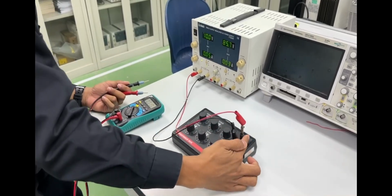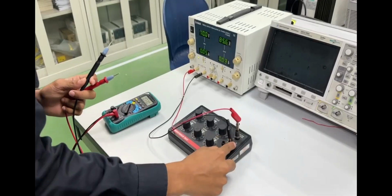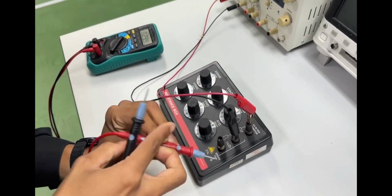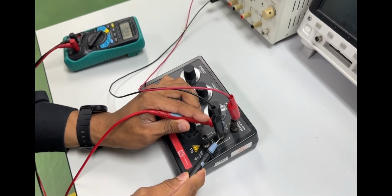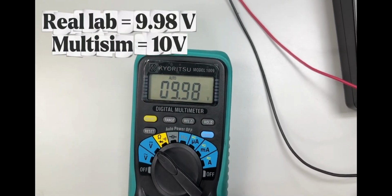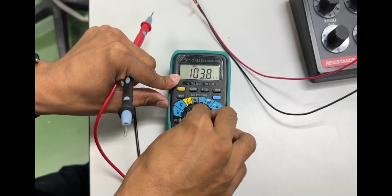For measure the voltage, we put from the DC supply, which is the positive probe, into the positive resistor. This one, and then for the negative probe, we put to the ground of the resistor. So positive probe we put at the positive resistor, and the negative probe we put at the ground. So the multimeter will show approximately 10 volts, between 9.98, like Multisim.